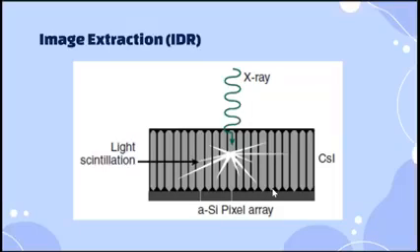Forming vertical crystalline channels in the cesium iodide layer was developed such that the crystals lie vertically, forming light channels that confine dispersion of the light somewhat. Okay. Nonetheless, the resolution achieved is still not as good as with a direct conversion system in which electron holes drift directly downward to the TFT detector.